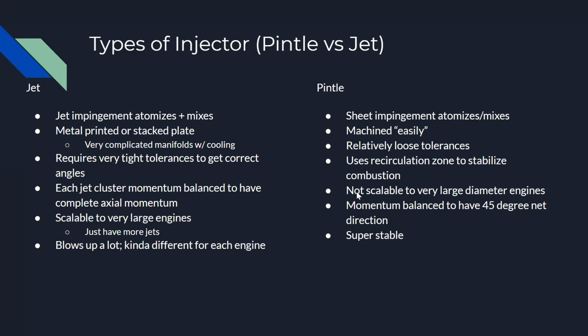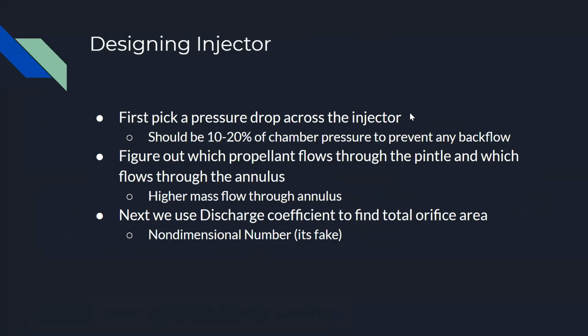I would kind of disagree with this. They can be scalable. They're not quite as scalable as showerhead jet injectors. But once you get pretty big, pintles get pretty wide and less efficient, since all of your propellant is coming out only in one donut shaped area. All right. Let's move on.